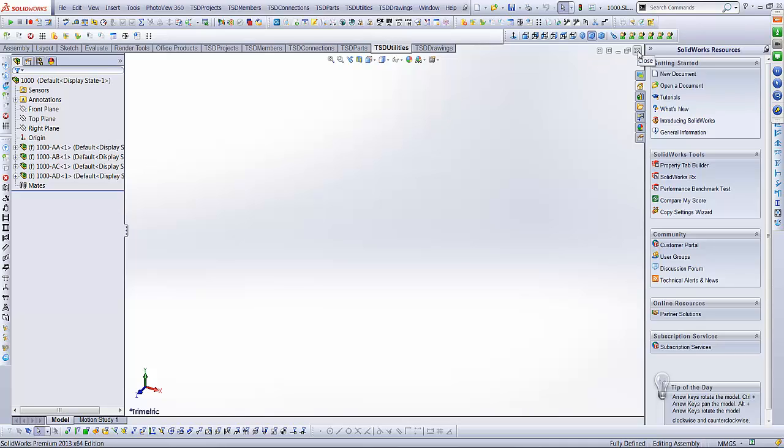Now if you understand the SolidWorks principles, we would create a driving sketch next, and the driving sketch itself would be placed in all of these areas and this level as well. The reason for that is that if I'm the lead project designer, I want to have control over the driving sketch, so that when I make a change, the other areas that people are working on will automatically update. It can also be detrimental if you're not careful about how you change your driving sketch. So the control belongs to the lead project designer.